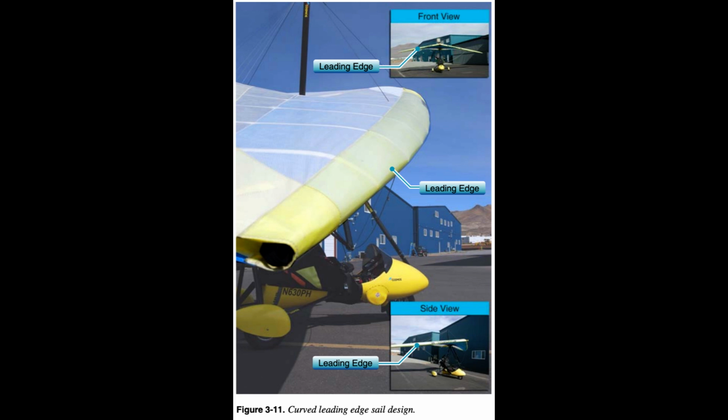Battens and leading edge stiffener. As discussed in the aerodynamics section, stiff preformed battens are the airfoil ribs that maintain the airfoil shape from the root to the tips. Additionally, a foam or mylar stiffener is inserted in a pocket at the leading edge to keep a rigid airfoil shape between the battens from the leading edge up to the airfoil high point. Double surface wings have additional ribs on the bottom surface that are straight or formed to maintain the bottom surface camber.